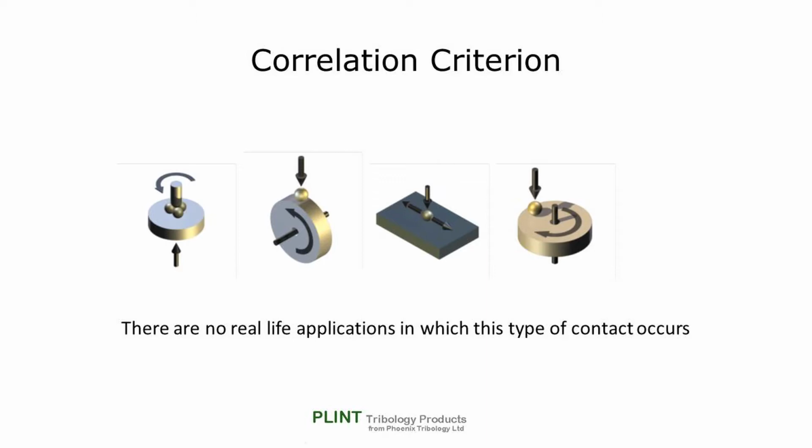Most practical engineering surfaces are designed to wear, not fail. Many sliding Hertzian point contact tests start by failing the surface and running on a failed surface, or, to be more precise, subsurface. However, there are many tribological tests using sliding point contacts. It should be obvious that these tests do not model anything in the real world.